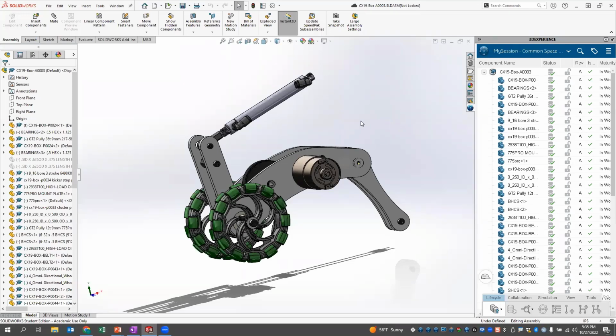So a very good question popped up. Sometimes when I open SOLIDWORKS files in 3D Experience, I can't see the same features that I can in SOLIDWORKS. One of the things I mentioned in the beginning is all the X apps are designed by SOLIDWORKS R&D, but they're actually designed on different kernels. So the feature history and different things, you will not be able to see if you bring a SOLIDWORKS part into the platform in X Design, but you'll be able to use them in assemblies. You'll be able to still edit them in SOLIDWORKS.